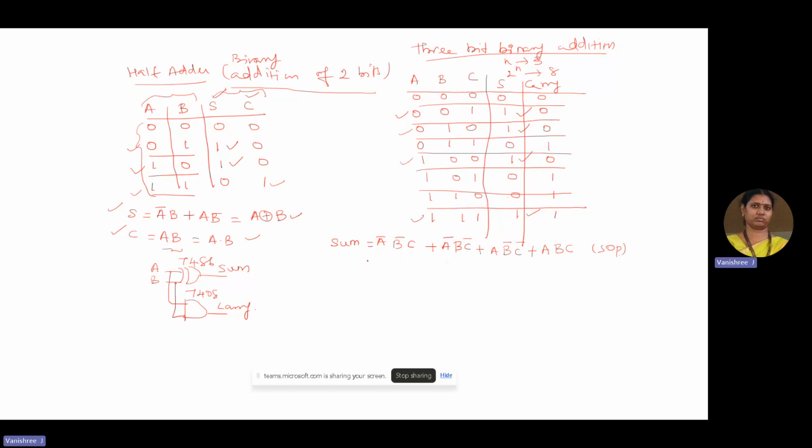So now let us see whether there is any possibility for us to take any common variables out so that we can reduce the expression. Because we would like to reduce the expression in order to reduce the number of gates required for implementation and thereby the cost required for the digital design. It is required to have a compact design and also with less cost.